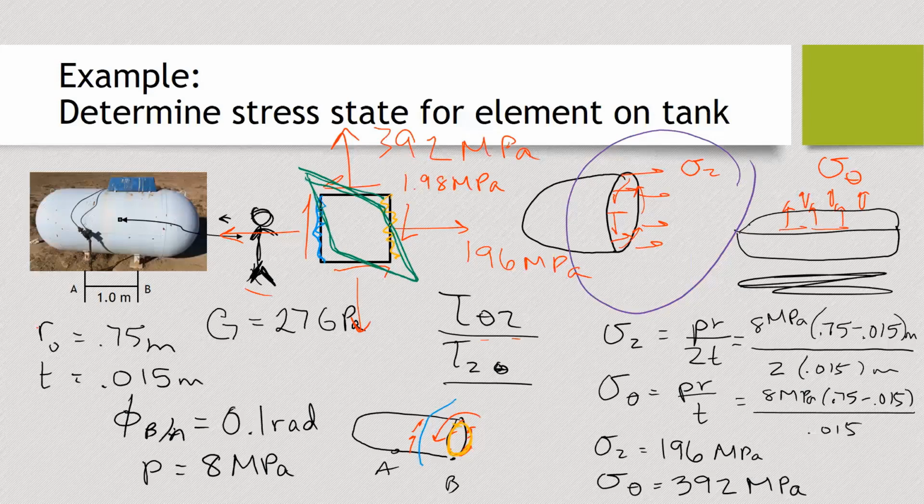You can see the way that those arrows are, they're going to push those corners out where the heads of the arrows are pointing. And so you can think about how these elements along the exterior of a circular shaft should deform. So if point A is back here by my left hand, and point B is up front, and point B is rotating counterclockwise relative to point A, so it's twisting like this, you can see the direction that those are squeezing.